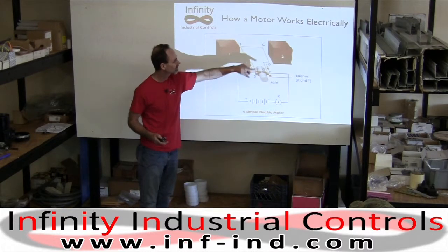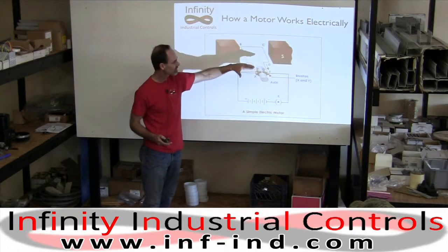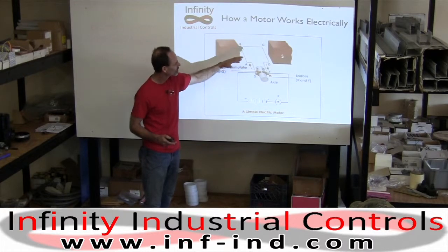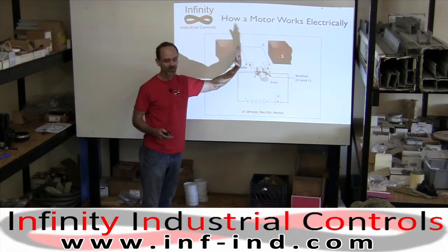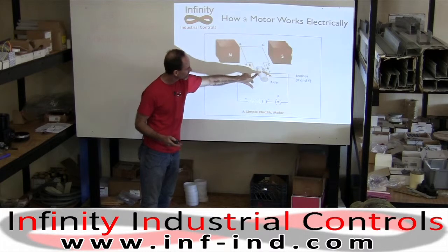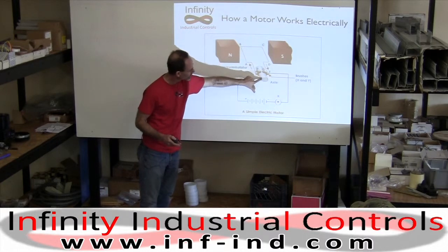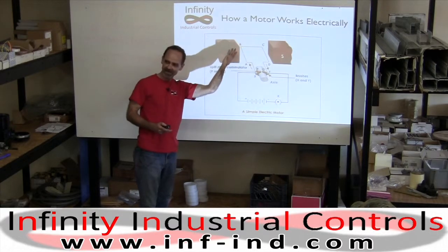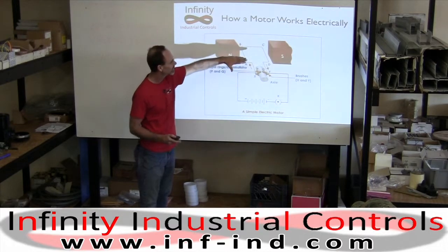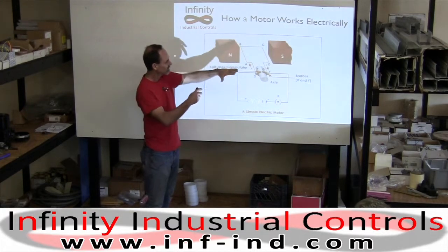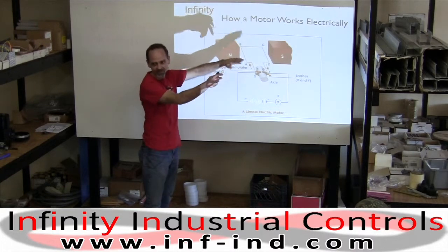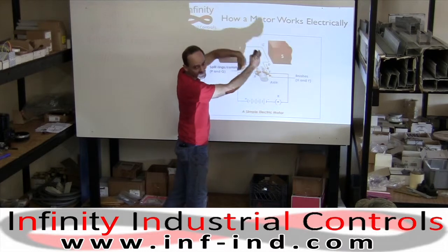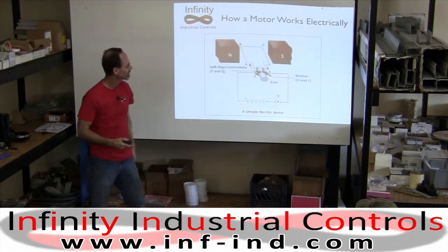Once you energize this coil, you have a south against south and south against north, one pulling, one pushing, causing it to rotate until this ring, now you notice it's split. Once it gets to the other side, it's going to reverse it, and then you're maintaining a magnetic difference so that positionally it's always pushing and pulling. So you get rotation constantly.